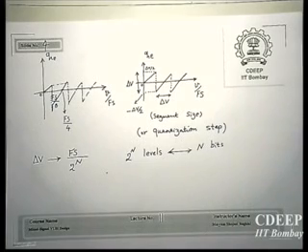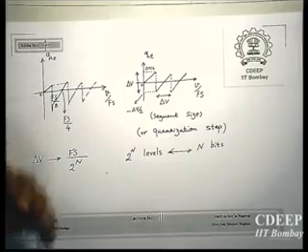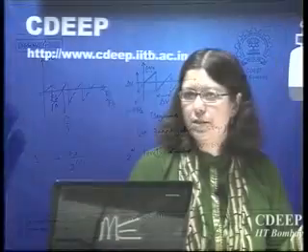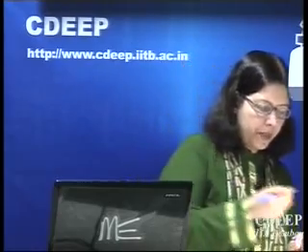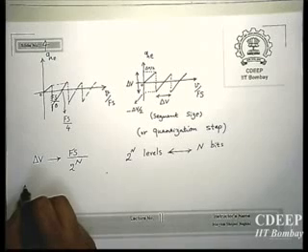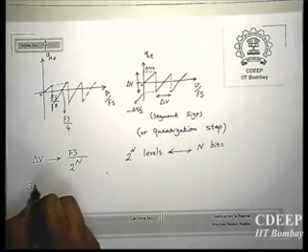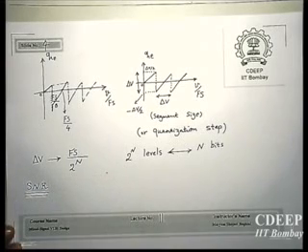You can look at this error as a noise. Suppose some noise is added to the signal in such a way its value has changed, and it always changes the value in such a way that it will be one of these quantized levels. So the first figure of merit that we talk about is SNR, signal to noise ratio.